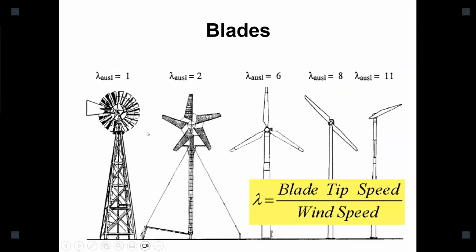There are many types of wind turbines. Single-bladed wind turbines are also used in some places. Did you see a two-bladed wind turbine somewhere? Maybe small wind turbines. Did you see a very small scale two-bladed one? Actually, some small scale wind turbine manufacturers use two-bladed turbines because they can reach very high RPM, so they can quickly comply with the generator without any gearbox and everything. There are some other disadvantages there, which I can explain now. Now you can see the single-bladed one has the highest efficiency.